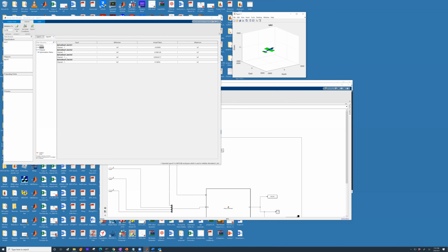Now, if you look at the trim value for the rudder, it is very close to 0. The trim value for the rudder is very, very close to 0, which means this trim solution would work for Zagi. This trim solution would work for Zagi because of the rudder trim case. So basically what it means is rudder is not used at all.